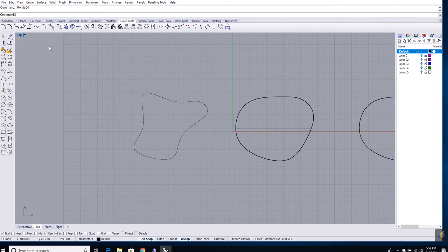And that's how you work with control points, and you can refine them. You can use O-snaps so that you can snap those points around. You can use grid snap if you want more control. There's an awful lot of ways to work with Bezier curves, so you're going to have to experiment with quite a few.